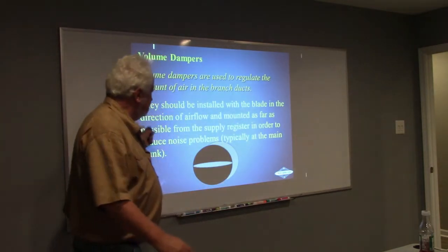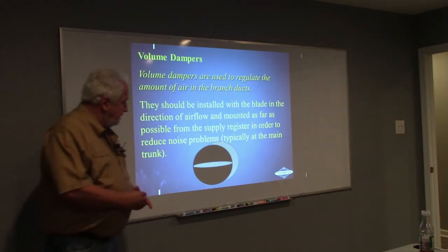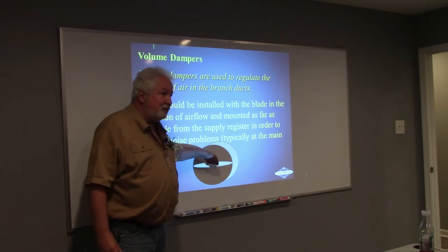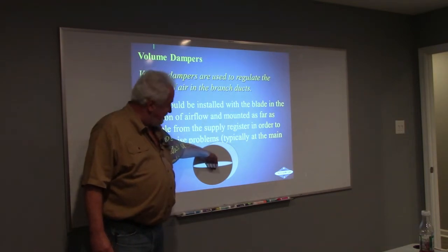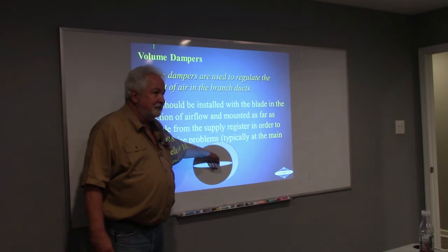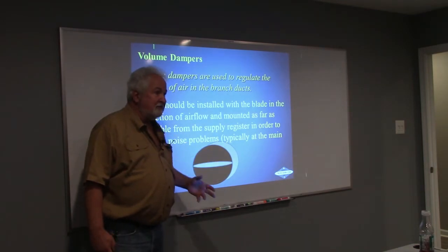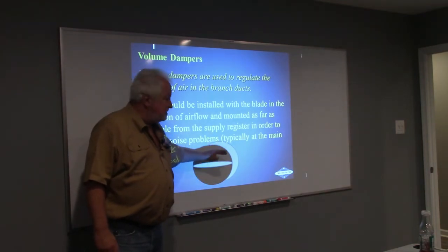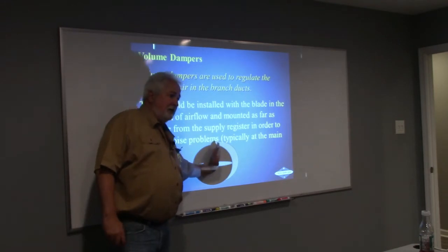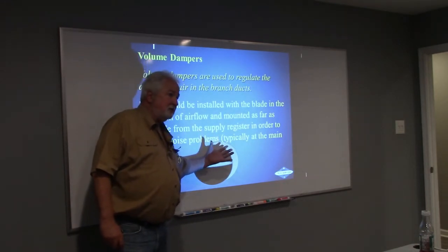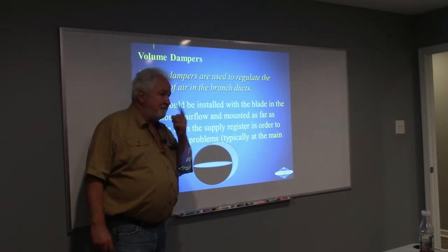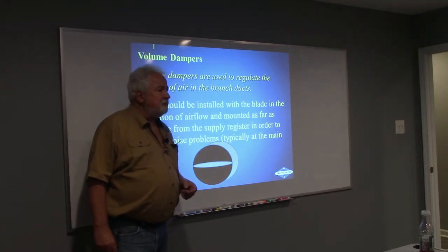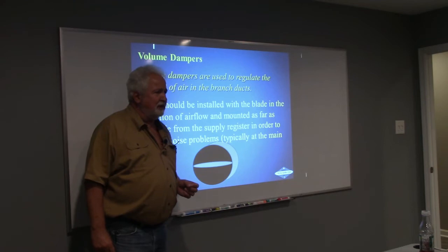Yeah. Cool. So again, if I had air coming up and I'm scooping it, how much of the duct am I actually using? Half of it. Absolutely. I might get air that I scooped out of it, but I still don't get near what I would have if I turned that this way and had static pressure. So pretty much you're going from an 8-inch to a 6-inch. Those are dampers and not scoopers? Nope. I don't believe in a scoop-it system. A scoop-it system is just trying to scoop the air and it doesn't ever work properly. Good? All right.